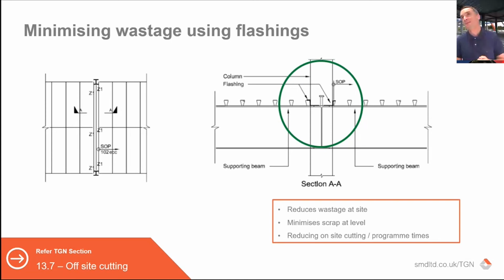Can I just interject? It's Bob from Sherwin-Williams here. Hi, Bob. Hi, mate. From our experience, if there is heat damage, you get like a brittle bubble, don't you, on the underside of the top flange.